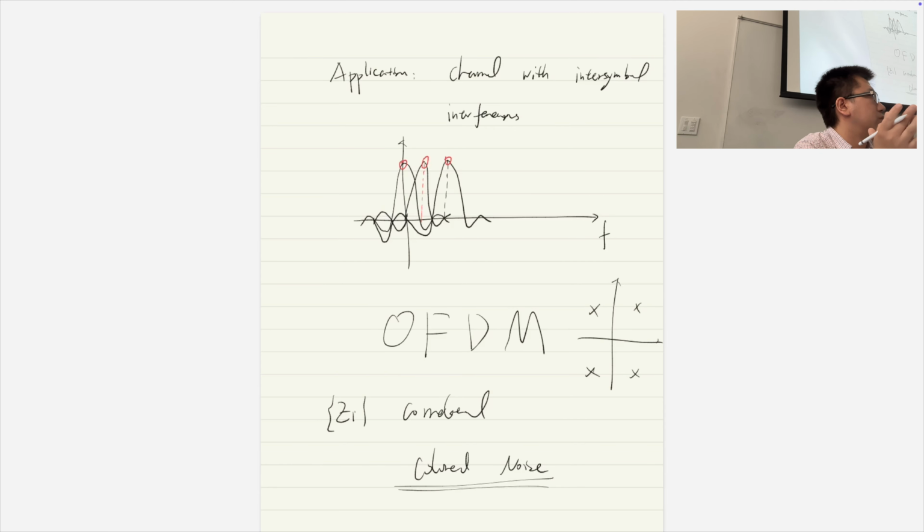The answer is no, right? Although you can still use it, it's not optimal anymore. Then somebody solved this problem using a very advanced concept called I-MMSE. I denotes mutual information, and MMSE is mean square error estimation. It's another technique in information theory, so we can develop another water filling algorithm called mercury water filling. We can make it practical, so it's not a problem.